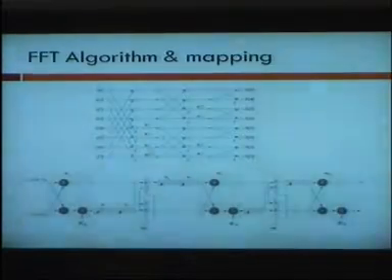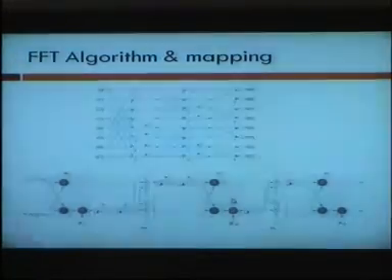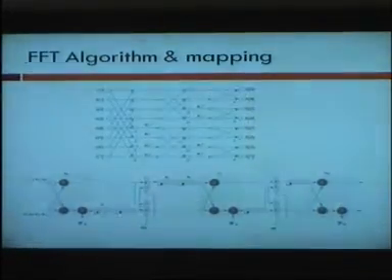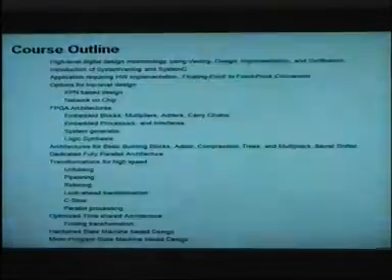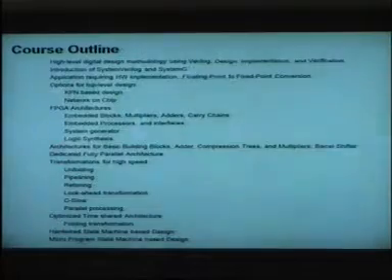Mostly you need to come up with a creative way of doing things, where you are minimizing your resources and just getting to the required throughput, whatever is required by your application. So that brings us to learning about unfolding, pipelining, retiming, the look-ahead transformation, C-slow retiming, parallel processing. And in many cases, it is quite the opposite, that you even need to do more than what the algorithm tells you to do.